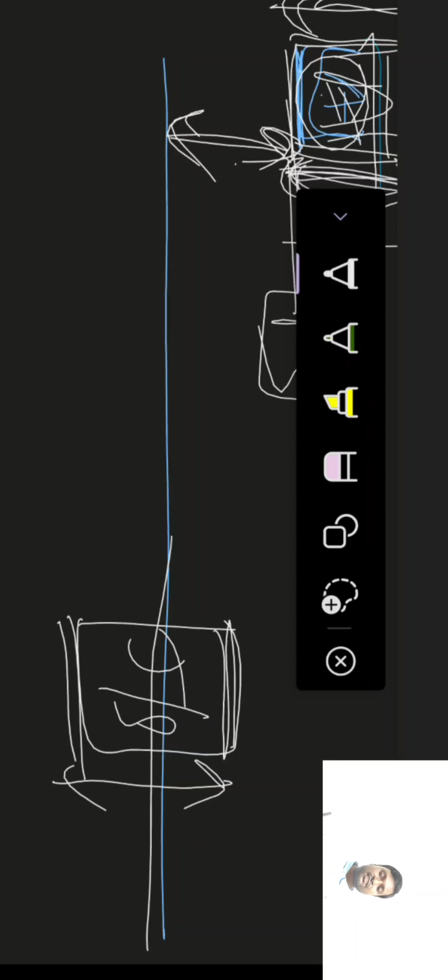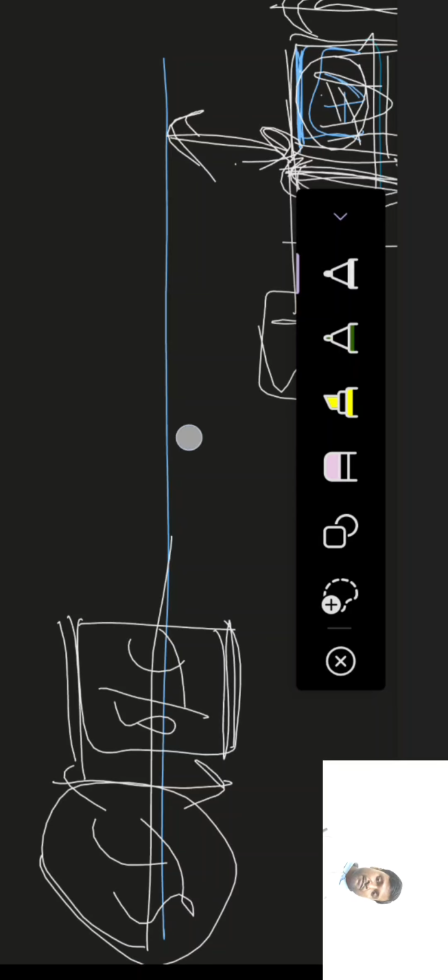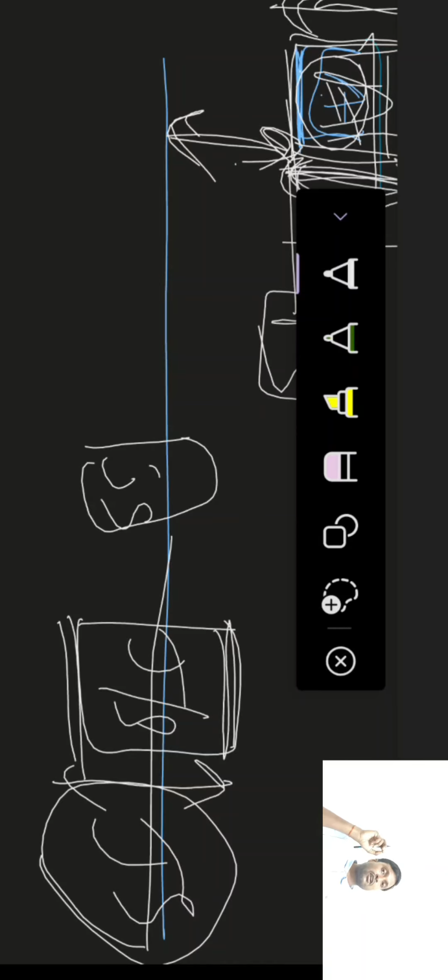So JS fundamental deviation, whether for the hole or for the shaft with small js, both will be bilateral tolerances. There can be other bilateral tolerances, like tolerance with fundamental deviation M. Sometimes it may not be a bilateral tolerance.